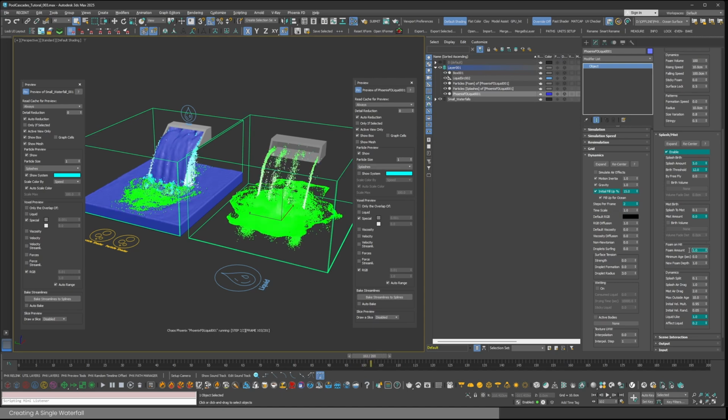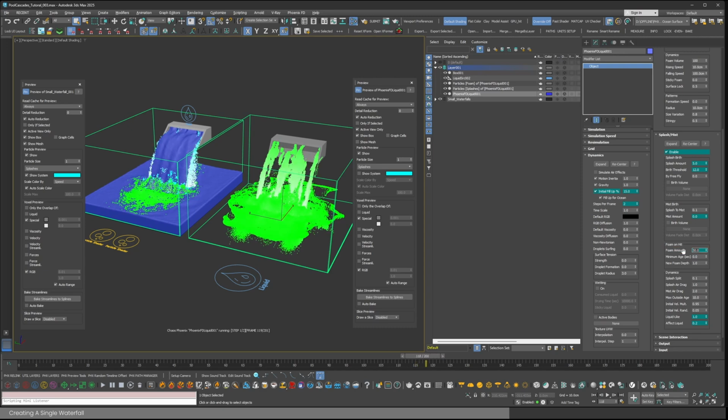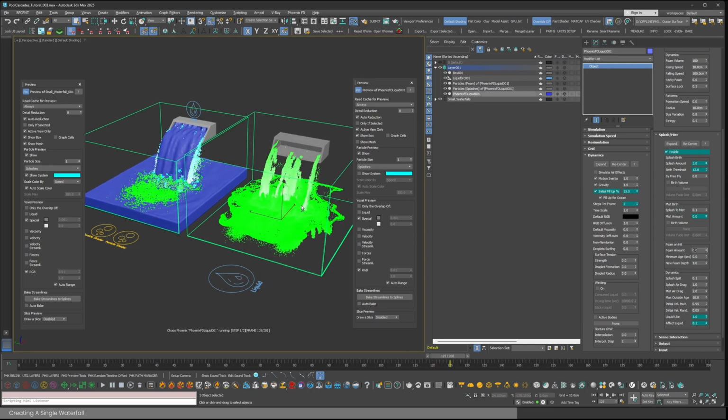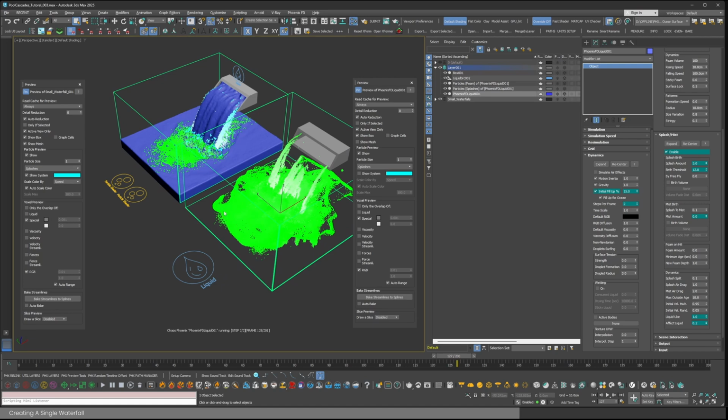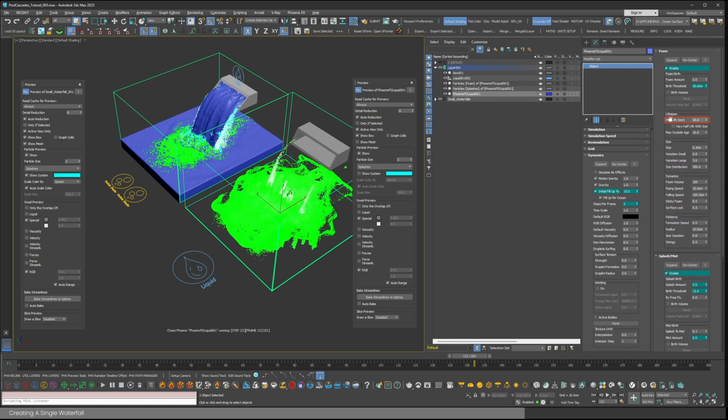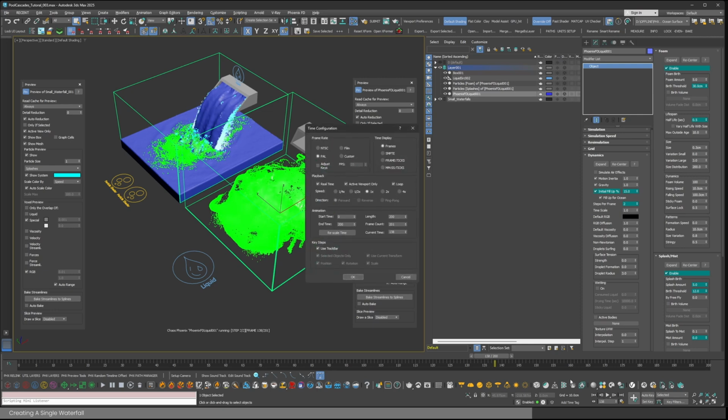If that's what you want, then great. You can even spawn more foam bubbles inside these voxels. I don't need that, so I'll leave this at 0. Right, what else? Seems like the foam lives for too long on the surface. The bubble's lifespan is controlled by the half-life parameter. The value is in seconds, so I can set it to half a second. My project is set to 25 FPS, so half a second is about 12 frames.